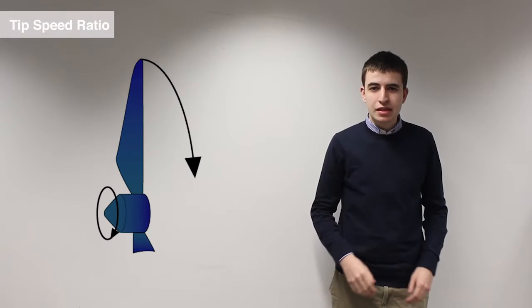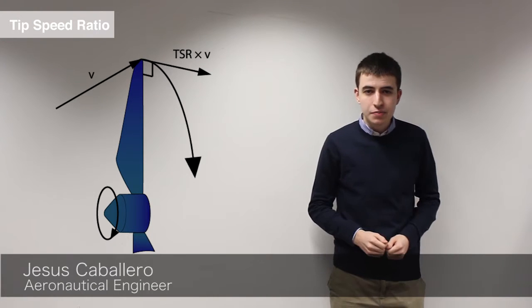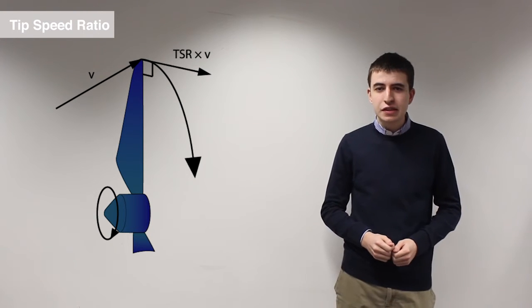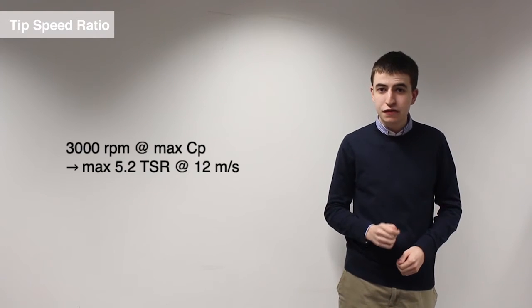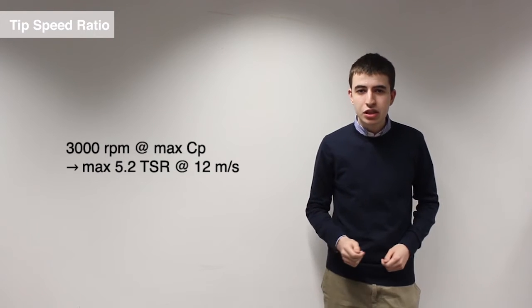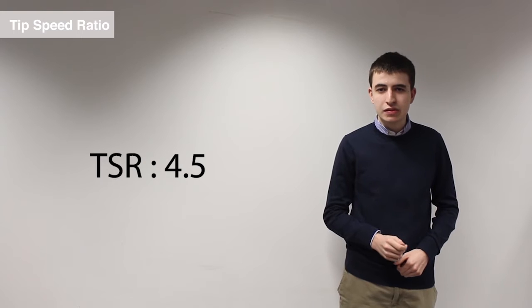The tip speed ratio is the ratio between the rotational speed of the tip of the blade and the incoming wind speed. In order to satisfy the requirement of 3000 rpm at maximum performance, the chosen TSR could not exceed 5.2. We decided to go with a TSR of 4.5 to make sure we didn't exceed the design constraints during testing.